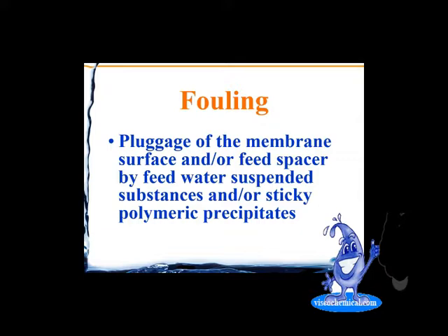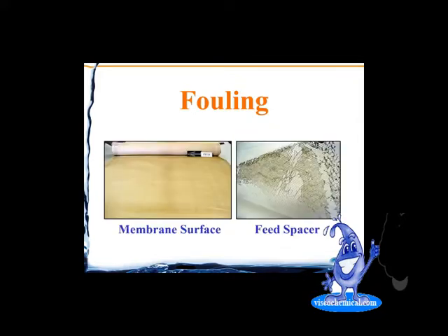So either the particles come in and don't leave, so they don't go out in the concentrate, they get stuck somewhere, or we also consider fouling organic polymeric types of materials, oils, greases, polymers, anything that can come in and doesn't leave. So it sticks to the membrane, sticks to the feed water spacer. So we call that fouling.